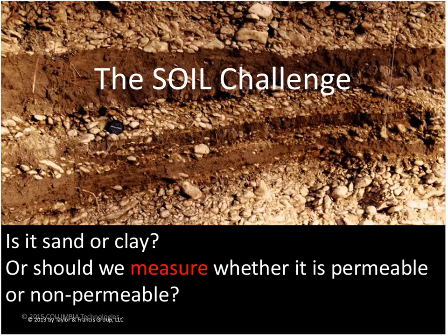Fifteen, twenty years ago, it was a simple problem. The soils were permeable down to the clays, and then they were not permeable, and that's what the oil was probably spreading out over. I will tell you now, over the last three to five years, I've removed the concept of sands or clays or silty sands or sandy silts from my vocabulary, because what we're really interested in, in the environmental business and the recovery business, is: is the soil permeable or is it not permeable? Will fluids move through the pore spaces or will they not? And if they won't move through the pore spaces, it really doesn't matter whether it's a sand or a clay.